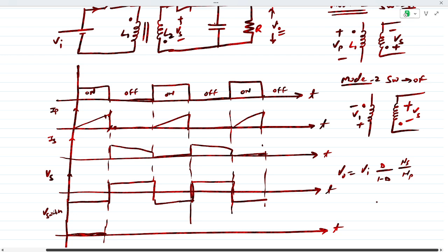And the voltage across any coil is basically L di by dt. So this di by dt means within 0 time the current is changing. So when we plot the voltage across the switch, it will have some peak here due to this action of di by dt, because within 0 time current is approaching the minimum value.